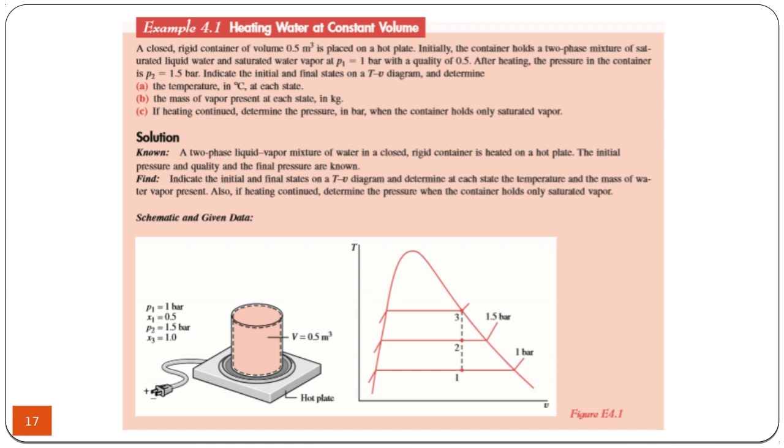And you have to be sure that you use the saturation tables if you are given the saturation temperature or saturation pressure, but you have to use both pressure and temperature if you are given a superheated vapor. So in the case of a superheated vapor, you have to use both temperature and pressure, or two intensive properties, let's say.